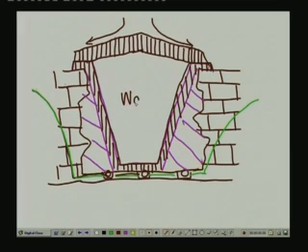So this is the waste that is totally covered on all sides by impermeable barrier. And so basically here you are not allowing any water to enter the waste material. That is one of the ways in which the possibility of harmful chemicals flowing along with the moving groundwater from the waste into the aquifer is eliminated.